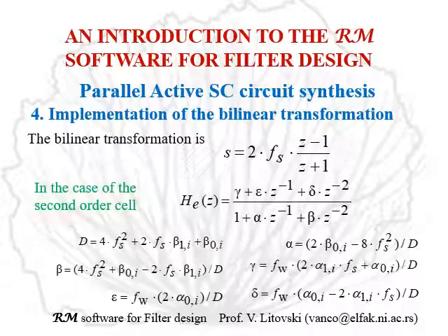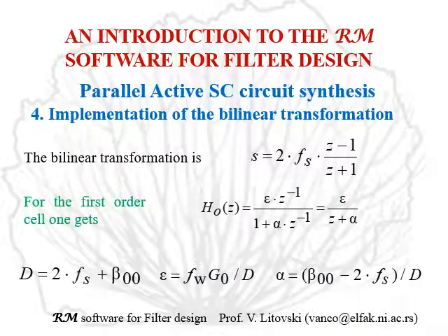After implementation, the second order cell becomes like this shown here. Below are formulas which are explaining the calculation of the coefficients of the biquad in the Z domain. This is the same story, but for the first order cell.